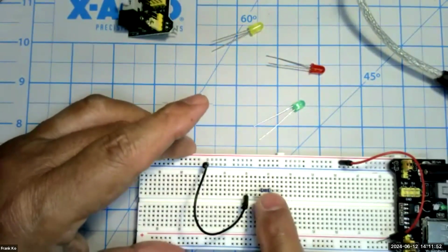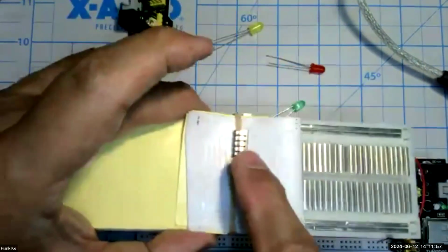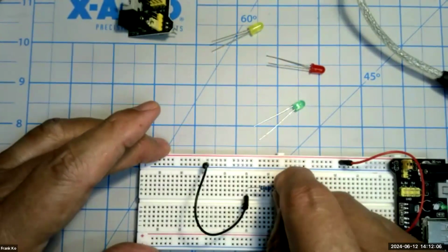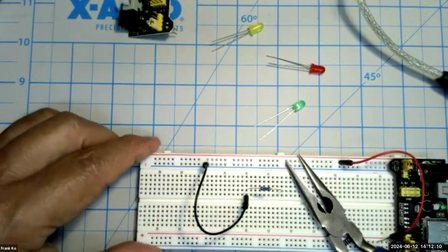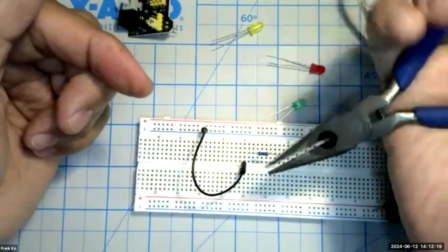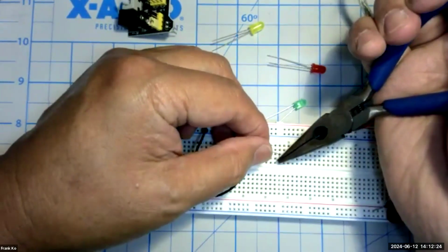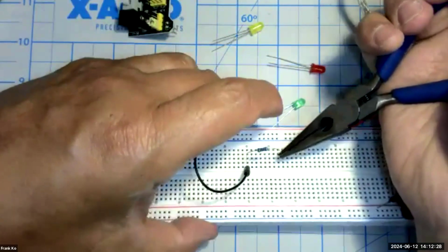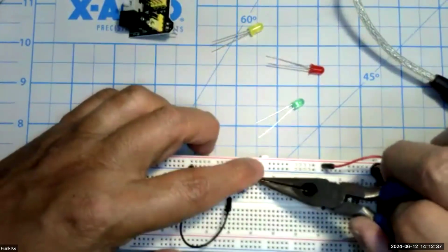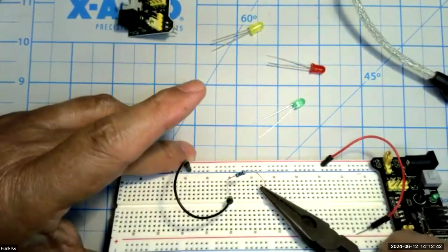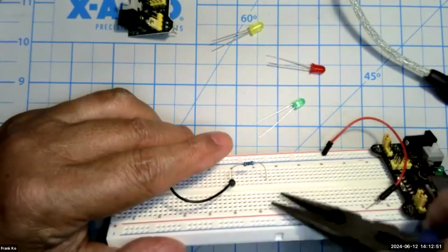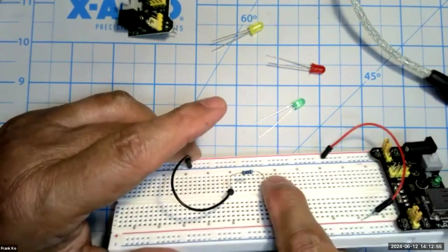Now, if you find your pinholes to be very tight because your wire sockets are brand new and the spring might be very taut, and you can't push this down carefully, hence comes your needle nose pliers. The needle nose pliers are very handy. Notice I'm grabbing this from an underhand position, spring loaded so that I can squeeze to grip, and once I let go, the jaw is open. So I can grab the resistor very near the end of the wire, guide it into the specific tie point of interest and push a little bit, and then a little bit, and a little bit. By gently pushing this way, it will give you a nice connection with the least amount of crumpling of the wire.